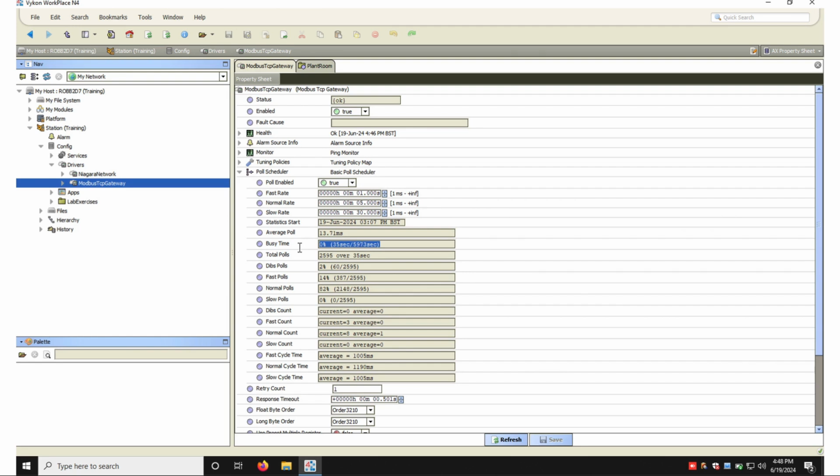And the physical comms line is very similar in this concept, that if we start hitting the messages too hard, then we're going to fill the line with comms. It gets busy, and if we start trying to put more and more messages in, it's not going to be able to handle all of those comms. So if you start to see a busy time above 70%, 80%, we want to start to potentially make a change to what's going on.